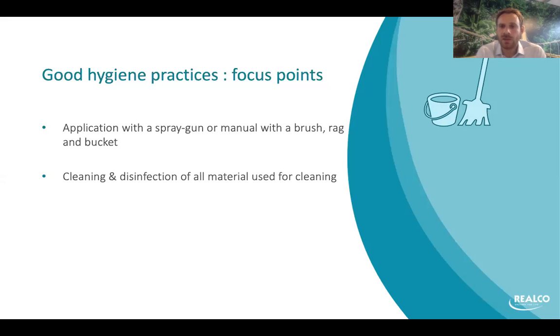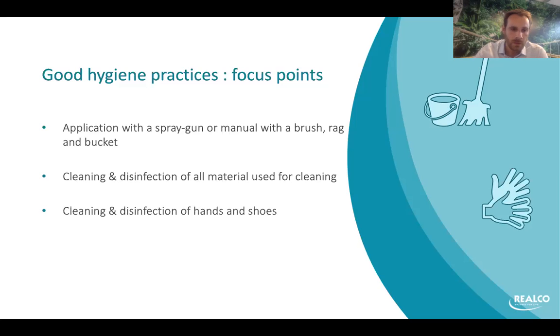And because you are not taking the time to clean them, really removing those pieces, cleaning them, and then applying a good disinfection, in fact, those equipment are contaminated. So it means that anytime you are doing the cleaning or the sanitation, it's even worse. In fact, you are bringing contamination into the production. So it's really important to take care of that.